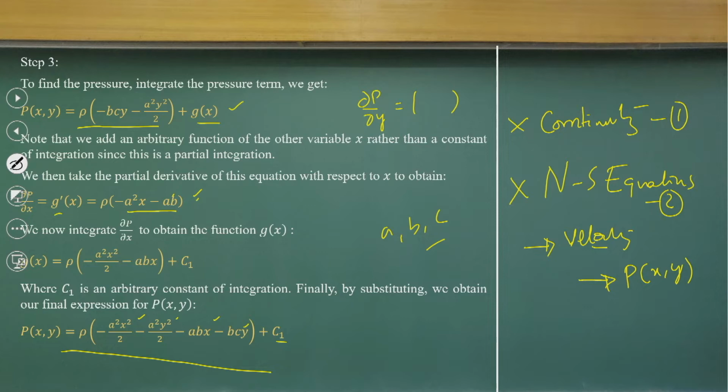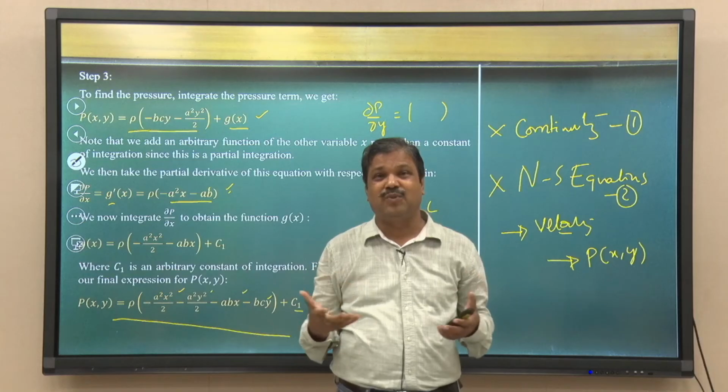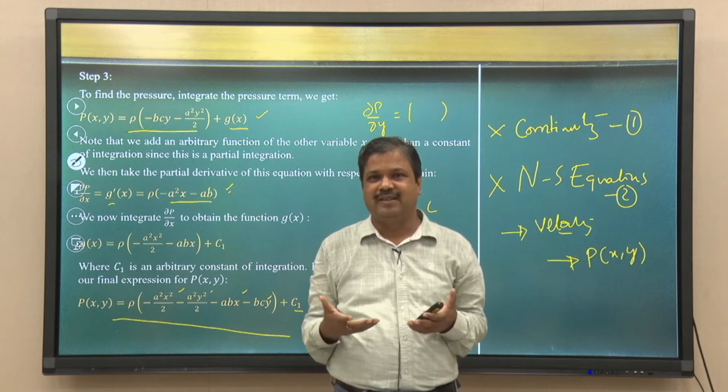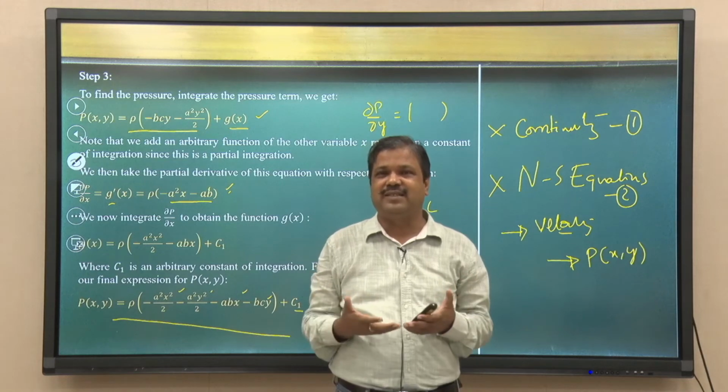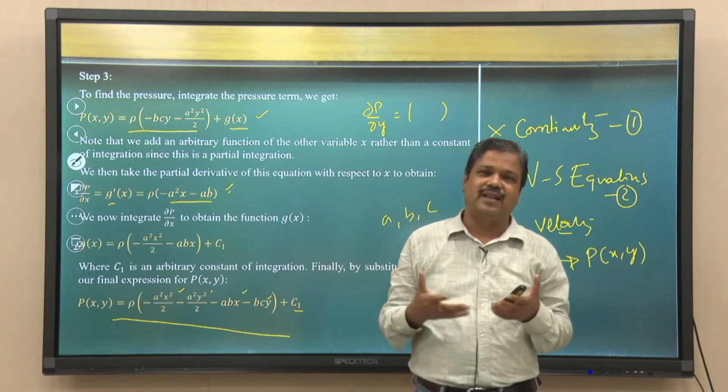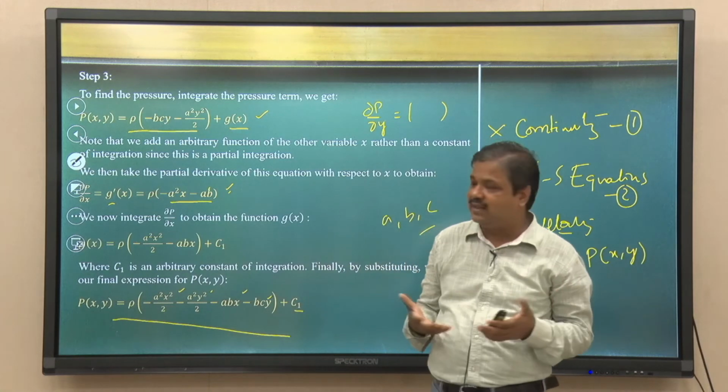Does it satisfy the continuity equation? If it does not, you need not estimate the pressure field, because the velocity is not representing a flow field.